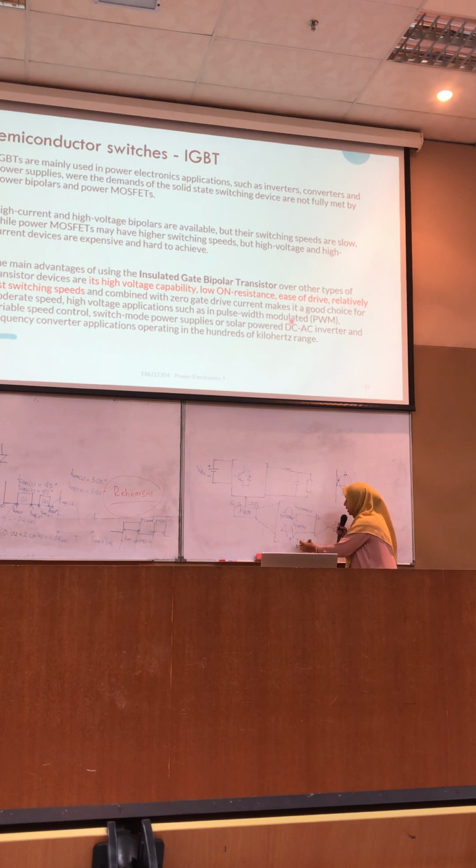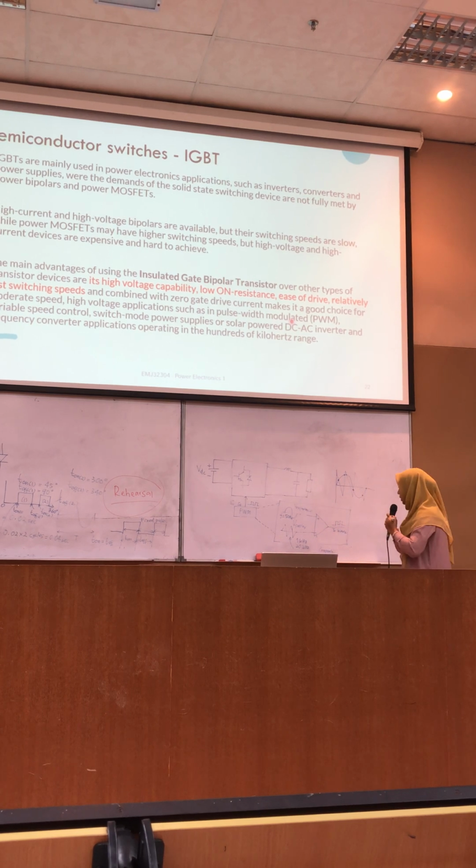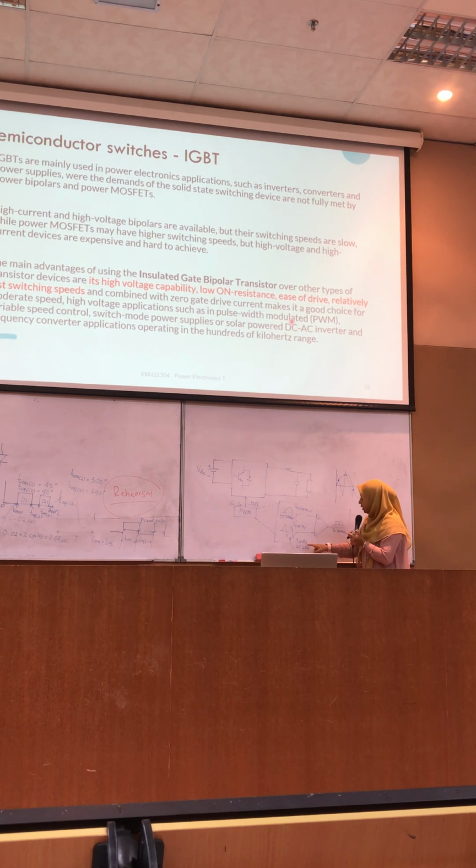So the smallest is 1 kHz, and you can go beyond that. That is why the application of PWM requires high frequency, because for the carrier signal, you need to have high frequency. Details about this we will look at later once we touch the inverter topics.